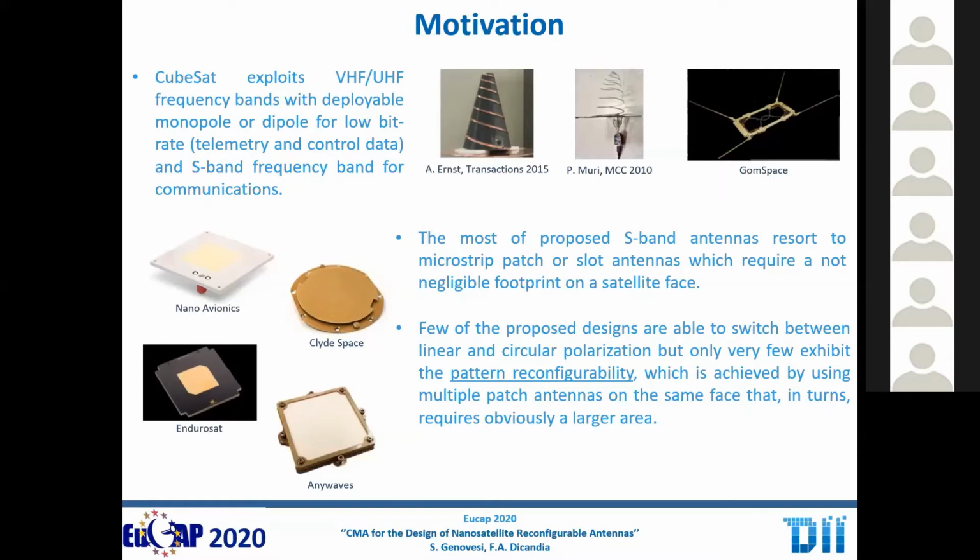And among the proposed solutions, very few are able to switch between linear and circular polarization, and even fewer are able to provide pattern reconfigurability, which is often achieved by using multiple patch antennas on the same face. So this requires, again, a large area. And sometimes also the analysis of the platform effect is done a posteriori, so this requires additional investigation.